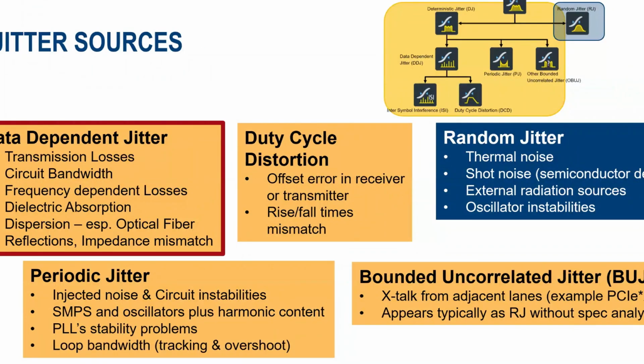The larger challenge for high bitrate systems is typically the data-dependent part because that's where more of the layout becomes a problem, and as higher bit rates occur in systems, you definitely need to be more careful about those losses. Periodic jitter is actually another subject which we won't really discuss today, but that's also a very big problem, often caused by the power delivery network and oscillations that occur there.